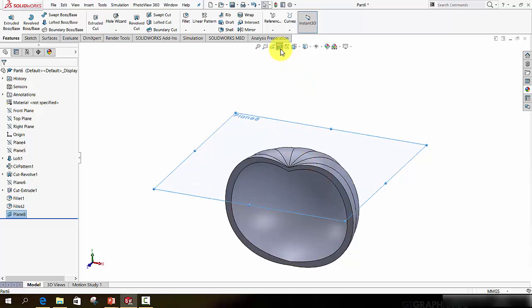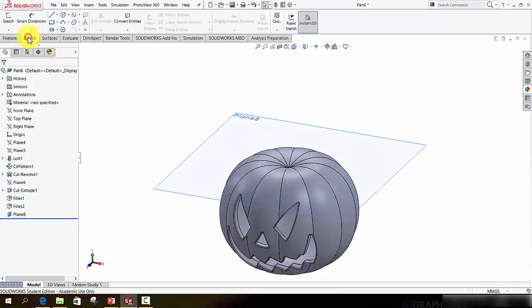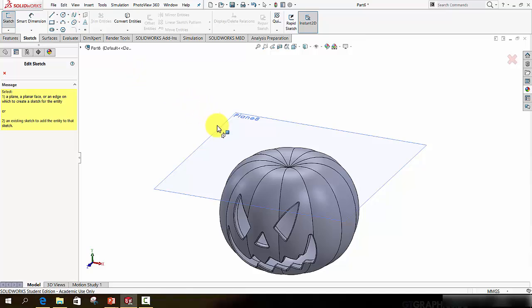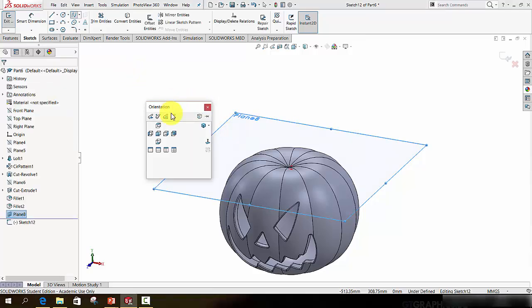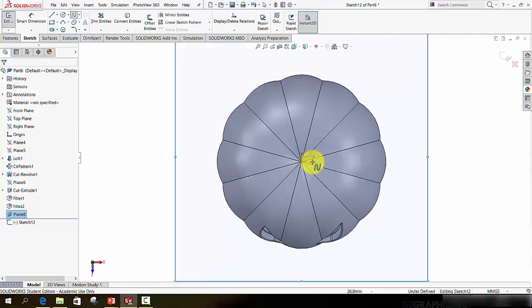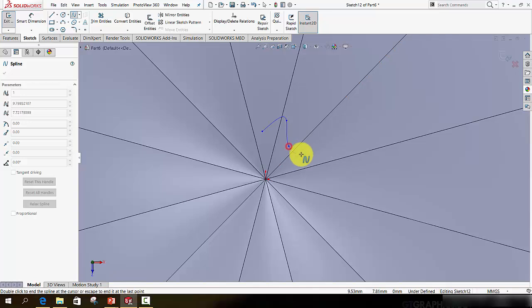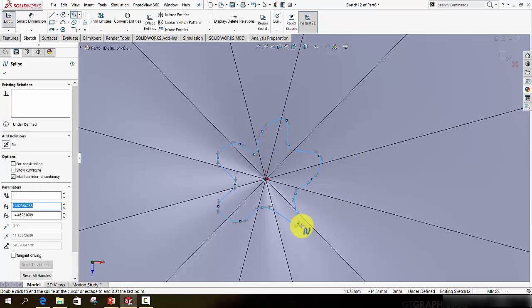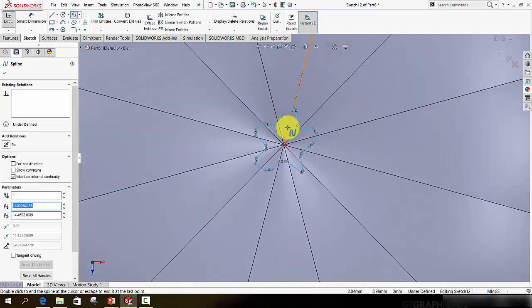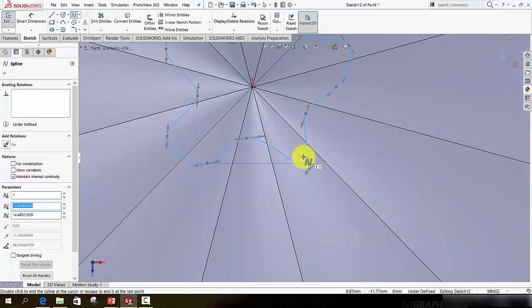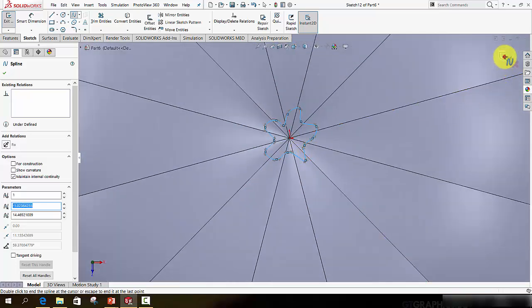So now I will turn off the section view again, and I will begin a sketch of a spline on that top plane. Press the spacebar and look 90 degrees to it, and then take a moment to draw an organic looking stalk-like shape on that plane. Now I could give measurements for this, but I don't want it to be something that is precisely defined. It's supposed to be organic, so it will grow in a semi-random shape as you see here.